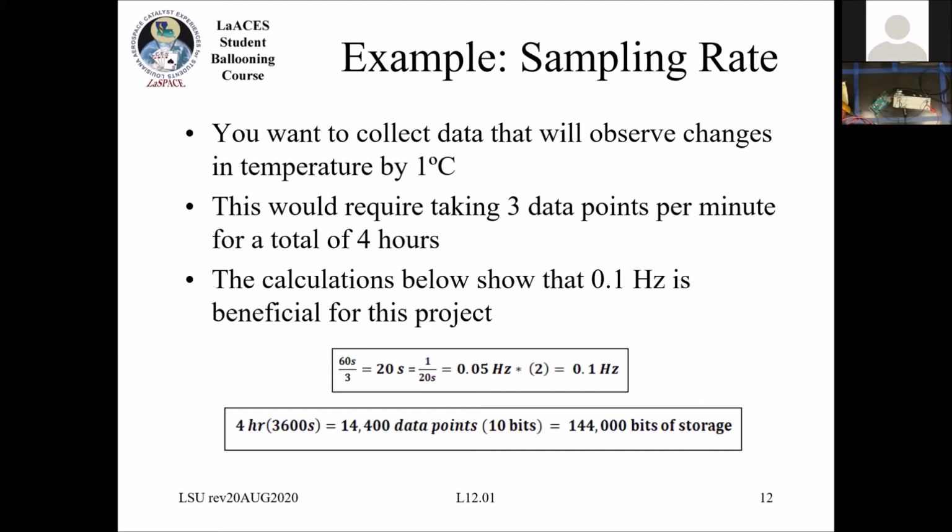So 14,400 data points is how many I expect to take. Each one of those is 10 bits. So I need this total amount of storage. But this is less than 1,000th of the capacity of the SD card. So we're not particularly worried there.